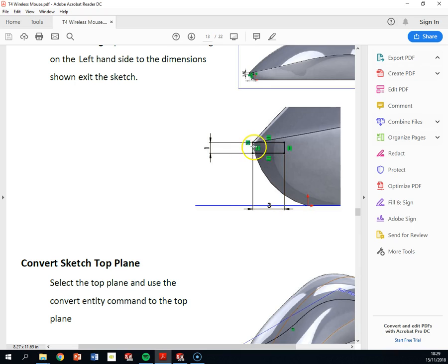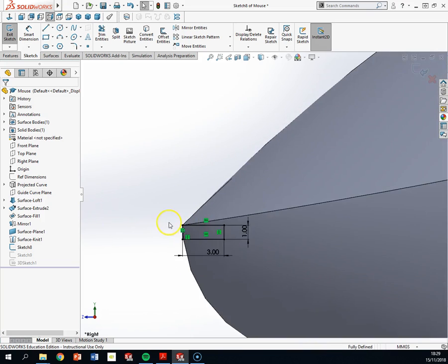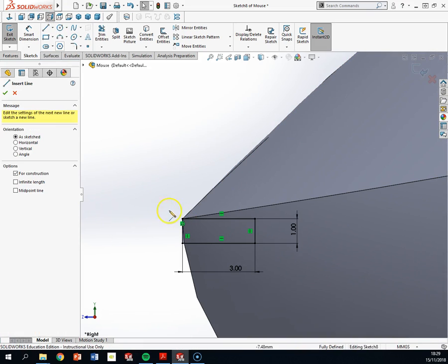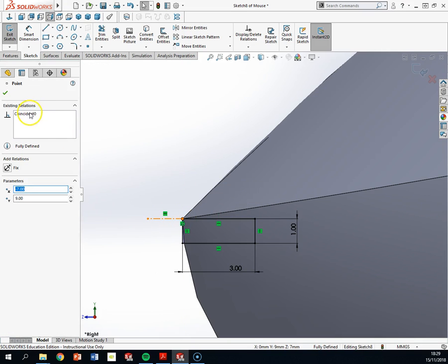Doesn't matter how far outside it, it's only the portion within the rectangle and to the body that will get cut. Okay, so moving back over, I'm going to go to my sketch. I want to keep it level with this point, but I'm going to set up a little center line here that's completely horizontal. This point here, I'm going to delete the coincident relation, and I'm just going to move this along.